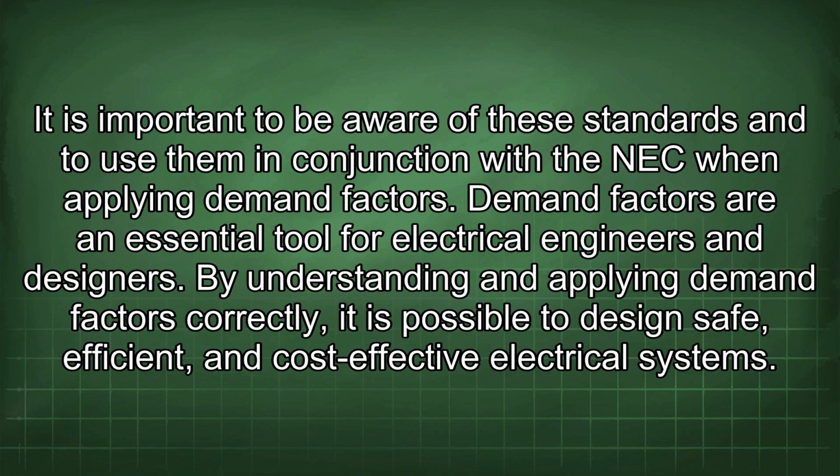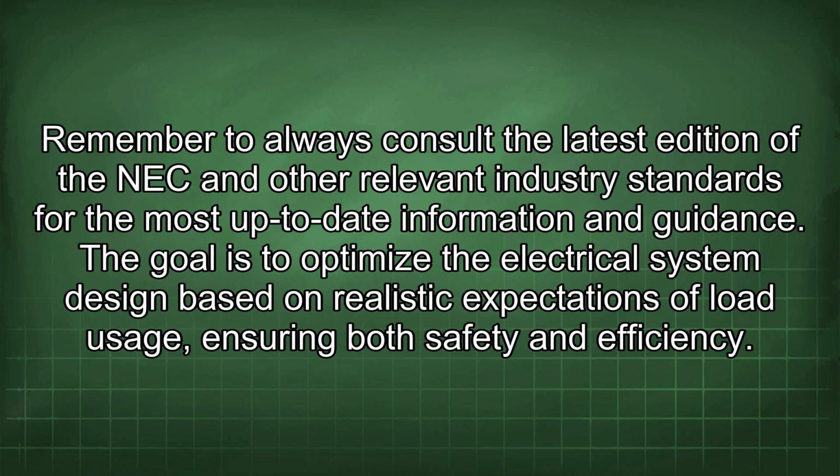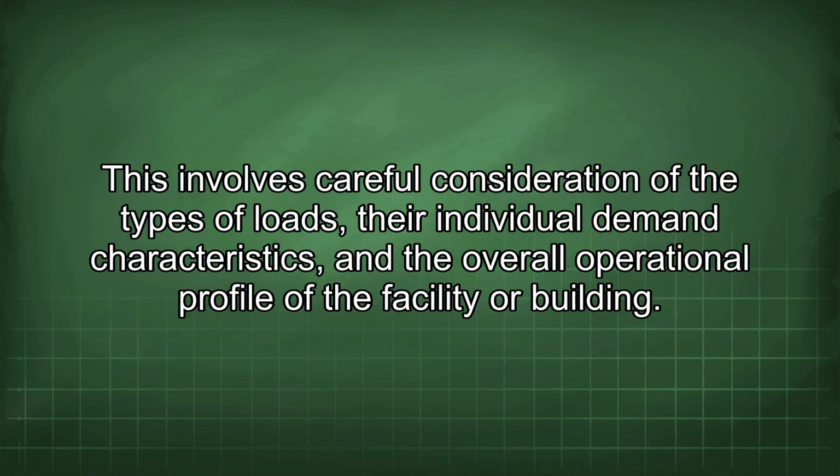It is important to be aware of these standards and to use them in conjunction with the NEC when applying demand factors. Demand factors are an essential tool for electrical engineers and designers. By understanding and applying demand factors correctly, it is possible to design safe, efficient, and cost-effective electrical systems. Remember to always consult the latest edition of the NEC and other relevant industry standards for the most up-to-date information and guidance. The goal is to optimize the electrical system design based on realistic expectations of load usage, ensuring both safety and efficiency. This involves careful consideration of the types of loads, their individual demand characteristics, and the overall operational profile of the facility or building.